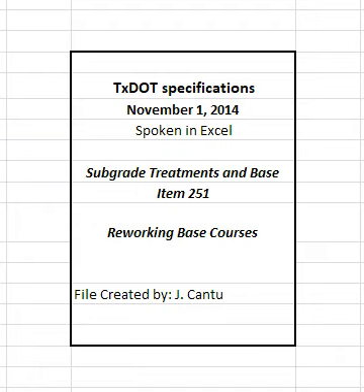When material is measured in trucks, the weight of the material will be determined on certified scales, or the contractor must provide a set of standard platform truck scales at a location approved by the engineer. Scales must conform to the requirements of Item 520, Weighing and Measuring Equipment.